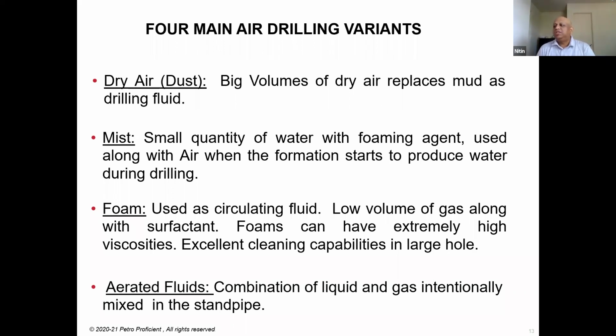You can just add surfactant, and there are some engineering calculations that need to be done to decide how much volume of surfactant you need to add, and some lab testing is also done, a small test to see the consistency and quality of the foam when it is generated. Basically, foam can give you very low density and very high viscosity. These are the characteristics of foam, and if foam is used, it can give you excellent hole cleaning.